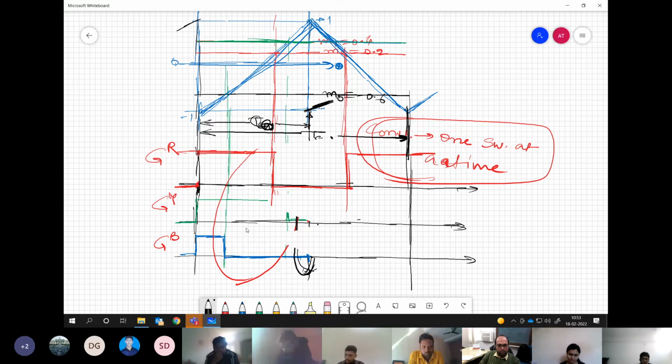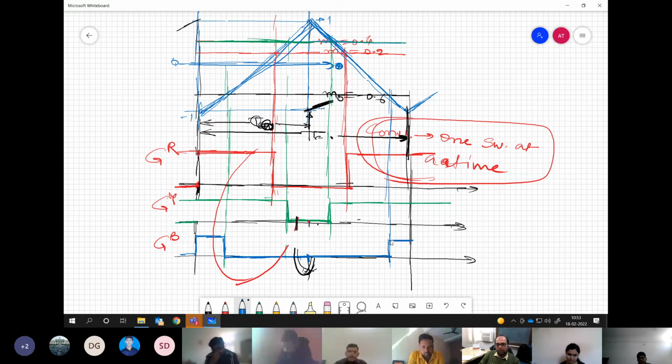Similarly for the Y phase, it will continue positive up to this interval, which is coming over here. The gating signal will go down during this and again continue as before. For B, the interval will be a little longer, and because we are realizing negative voltage, the off duration will be much longer, and then it will be high at the beginning and end of the cycle.